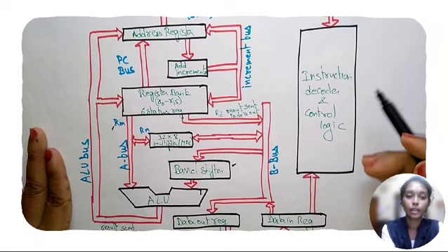This block diagram contains address register, address incrementer, register bank, multiplier, barrel shifter, ALU bus, PC bus, incrementer bus, A bus and B bus, data out register, data in register, instruction decoder, and control logic. We can see the execution of data. The register bank holds all the local registers. The barrel shifter shifts the data right or left, or rotates it. Here, the register bank is connected by the A bus and B bus to the ALU. The A bus is directly connected to the ALU, but the B bus is not directly connected. Here, the A bus and B bus are known as data buses.